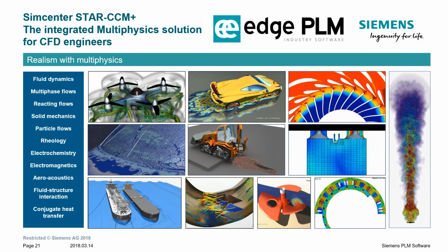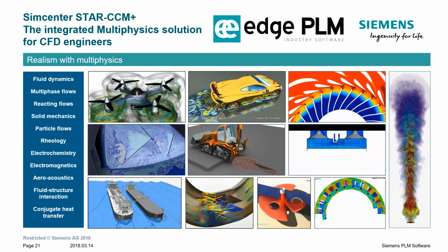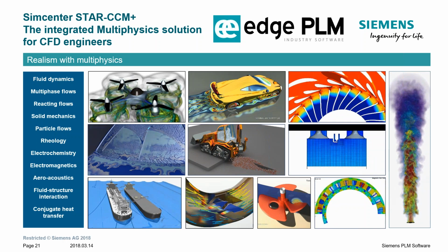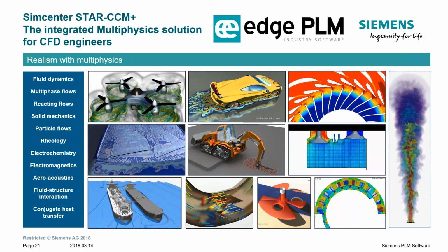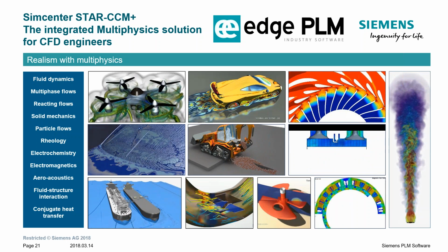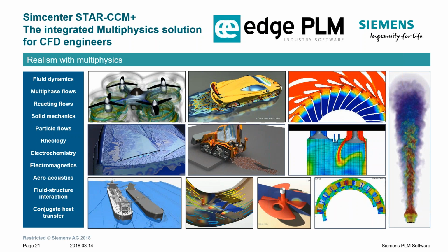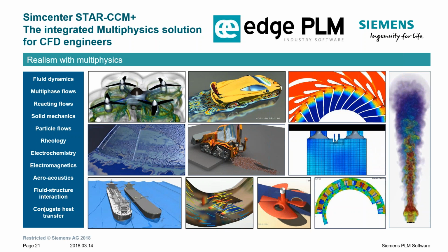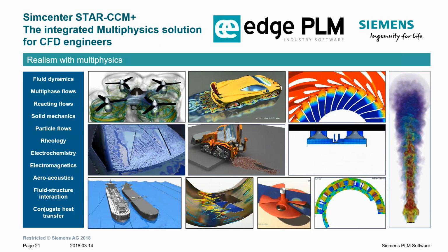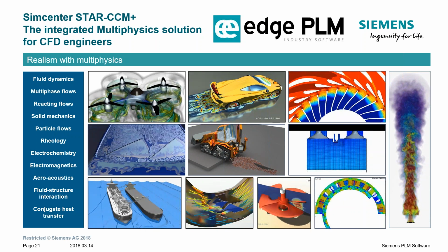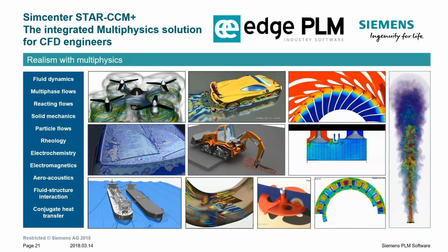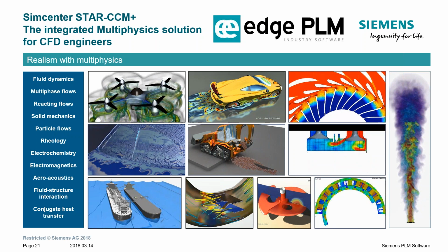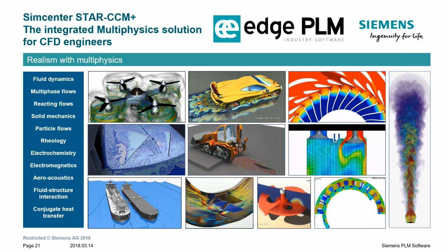Moving objects. Problems that involve multiple moving and interacting components can be easily simulated using overset meshing, mesh morphing, or a combination of both. The moving mesh capabilities can also be used for parametric studies and for steady or unsteady simulations, providing an easy way to reposition or replace objects to study multiple design configurations.